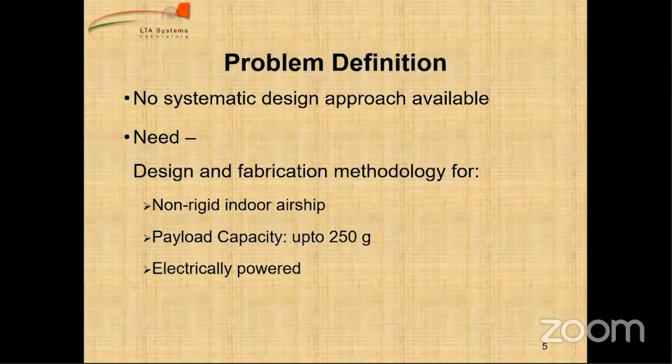So electrically powered, actually, I'm suggesting. If we use any other, like a piston engine, it can be the alternative option for the small sized airship. But in case of a piston engine, there will be difficulty in starting those engines. In case of electrically powered motors, we can start and restart again. We can stop when we want, and start when we want.